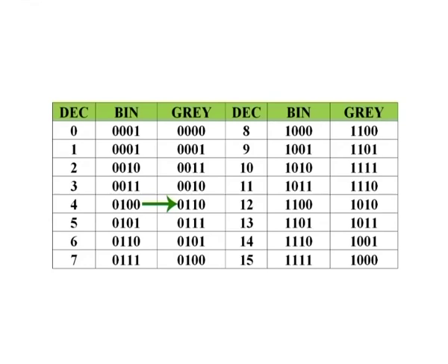An examination of the 4-bit Gray code numbers shows that the last entry rolls over to the first entry, that is, the last and the first entry also differ by only 1 bit. This is known as the cyclic property of the Gray code. Although there can be more than one Gray code for a given word length, the term was first applied to a specific binary code for non-negative integers and called the binary reflected Gray code or simply the Gray code.